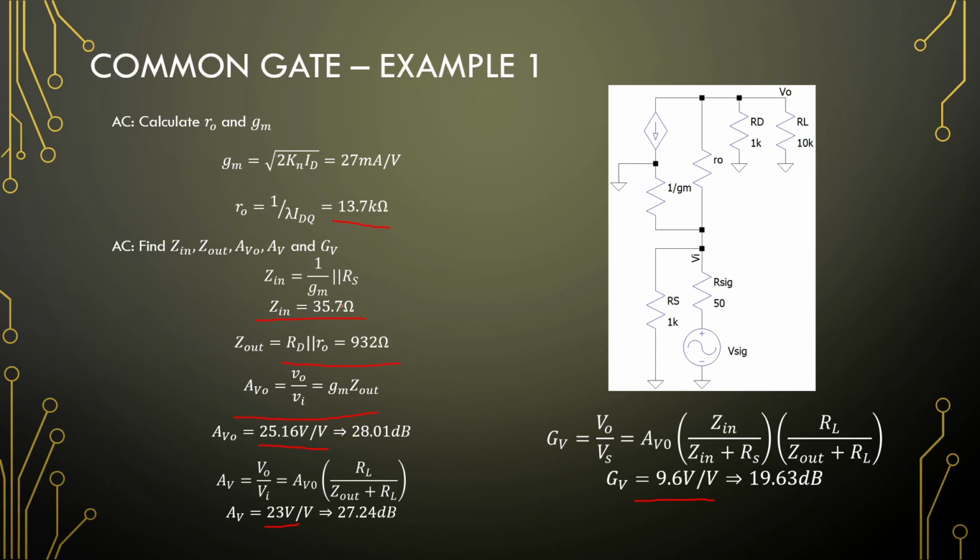Right. If we look at the input here and the source size that we're adding, the source size is about 50. This amplifier is actually a little bit mismatched. Typically, you want to design these with a matching input impedance and signal.